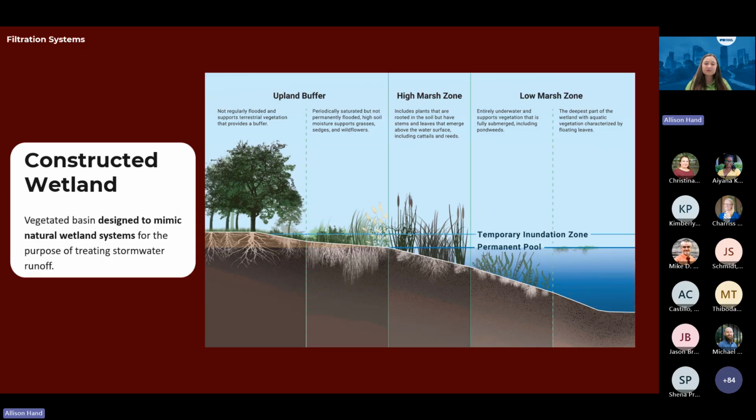While constructed wetlands work best when designed to serve a smaller contributing area, multiple cells can be designed to work together for larger areas. The constructed wetland design set provides considerations and recommendations for common challenges such as how to prevent mosquitoes from breeding in shallow waters, nobody wants that, how to prevent algae blooms, and how to handle sedimentation accumulation to maximize vegetation treatment and efficiency.